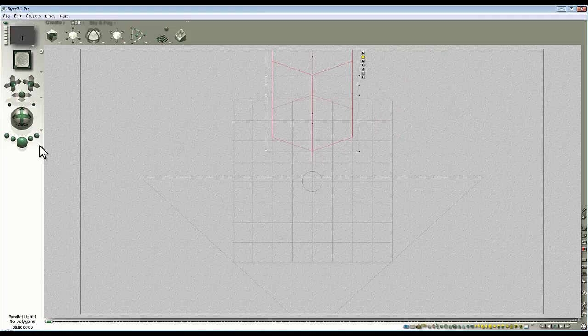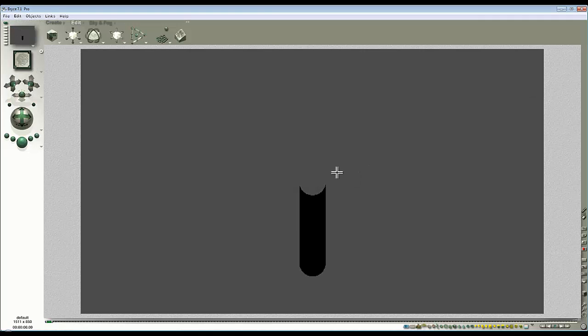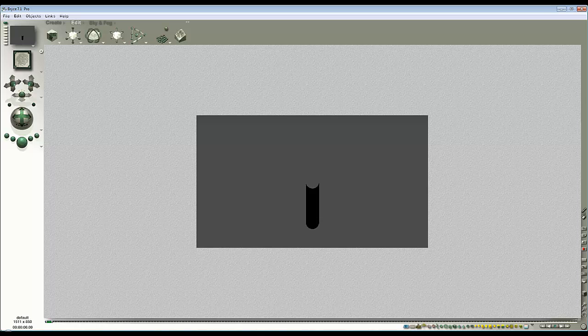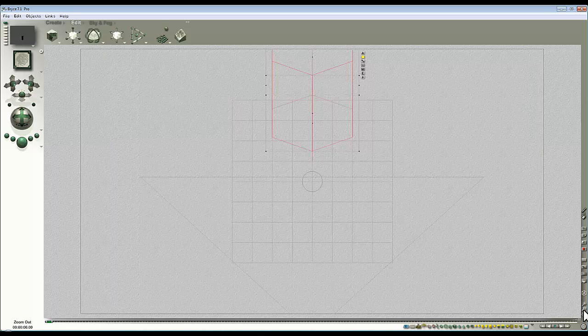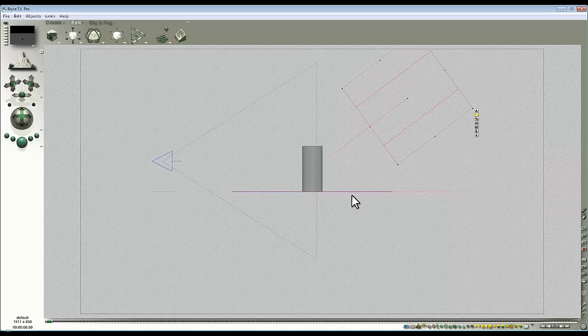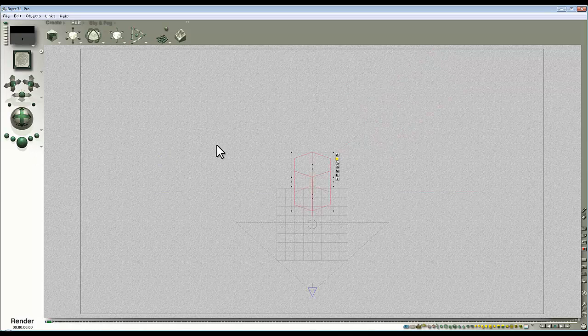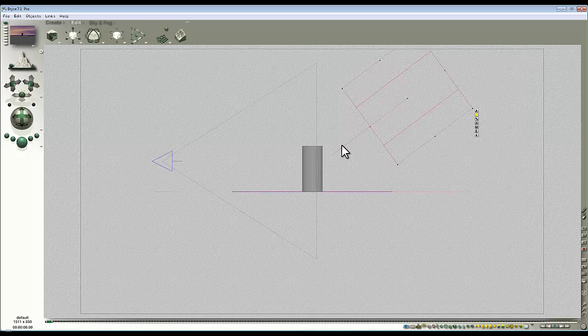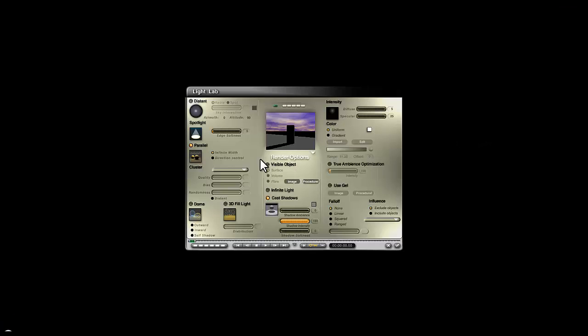So now it's very like having the sun in your scene, but I'll just zoom back. No, not zoom that out. I want to zoom the wireframe out. Zoom out a bit. You've got a cutoff point where the plane of light emission meets the infinite plane, and behind that you're not getting any light. Stranger things yet, you have the option of having a directional control. So at the moment the direction is directly above, and this does remember its settings, unlike the distant light, so you don't need to keyframe this.